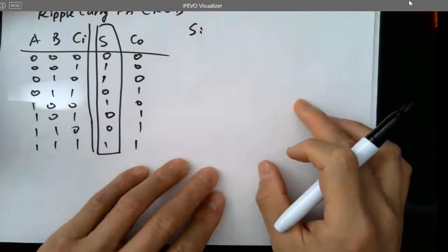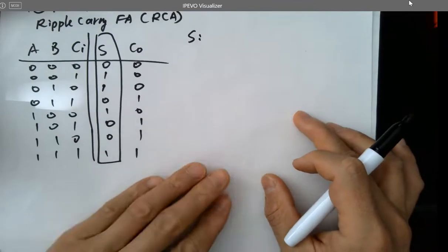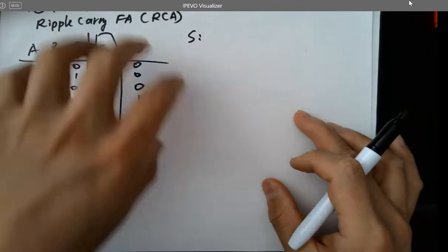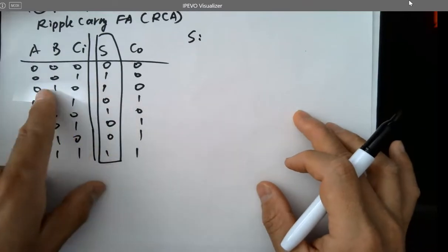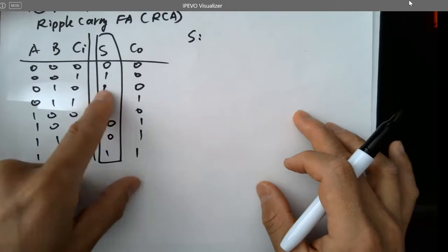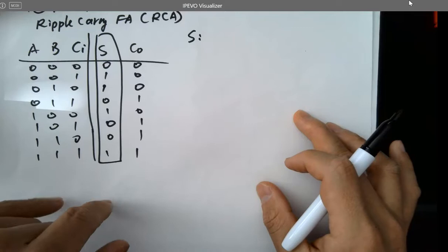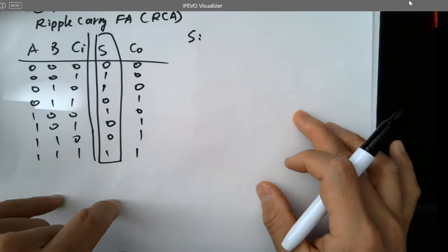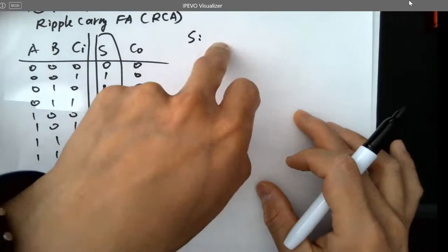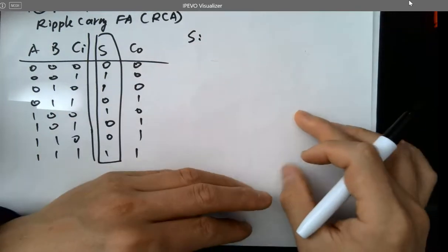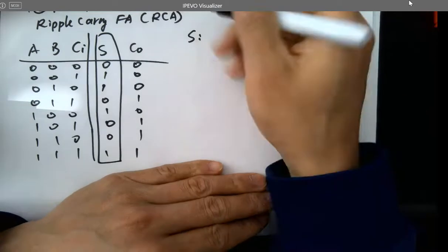Okay. So how to simplify this truth table, or how to simplify the logic? You have a truth table, you can list the logic equations by looking at the ones, and you can combine these min terms to make the logic equations. However, sometimes it's difficult to simplify the logic from the logic equations. So what do we want to use to simplify the logic? K-map. Okay.